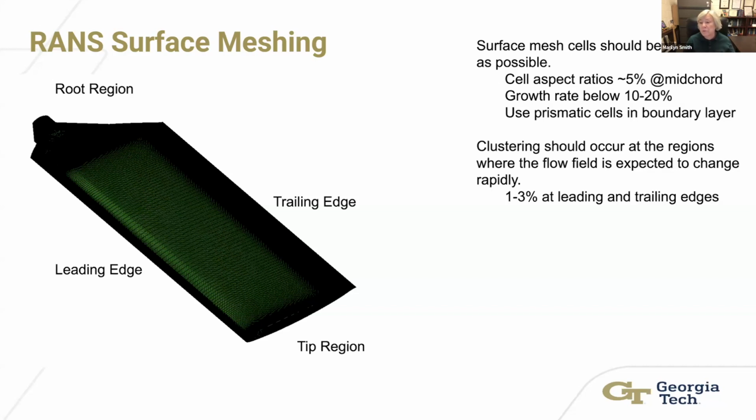The boundary layers you want to resolve as well as possible. And in fact, if you can get away with it, please use a structured mesh for these kinds of blades, because then you can go to a higher order scheme and use fewer mesh points and they're faster. So if computational time is an issue, deal with the more complicated mesh that a structured code requires.